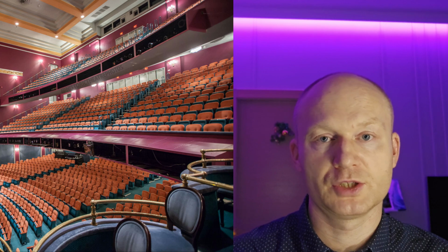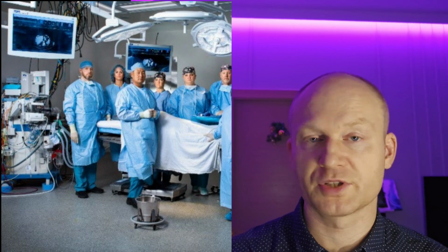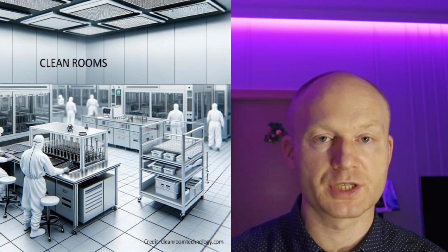It is used where the number of occupants is changing drastically, such as cinemas, theaters, and shopping malls. Intensive air exchange is designed for air purification, for example, surgery rooms or big kitchens. And intensive air exchange is designed for dehumidification, for example, swimming pools or water parks.